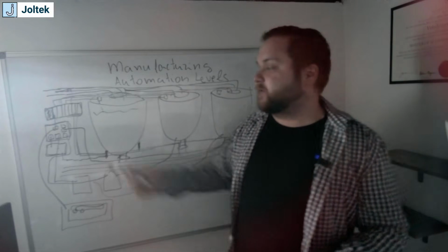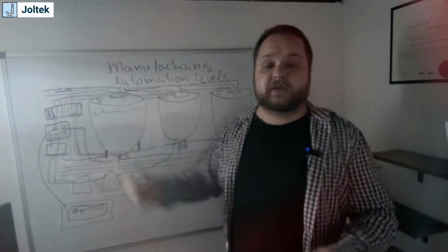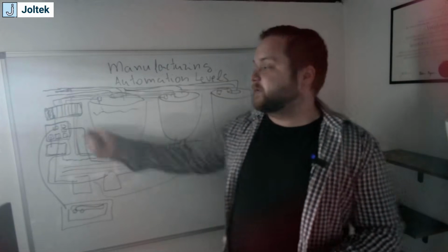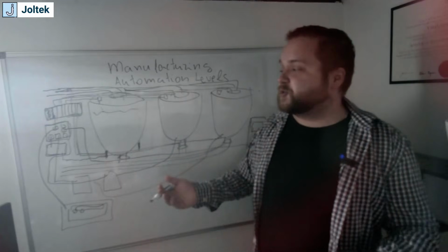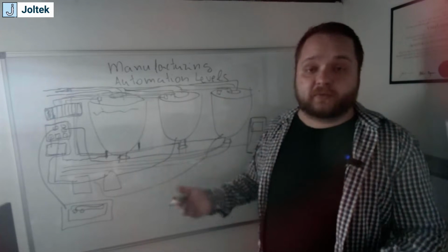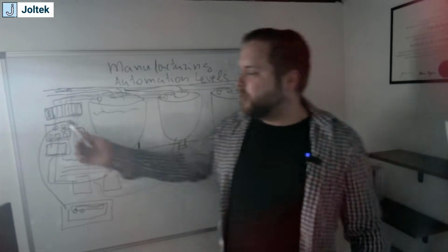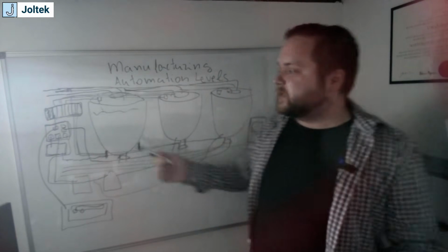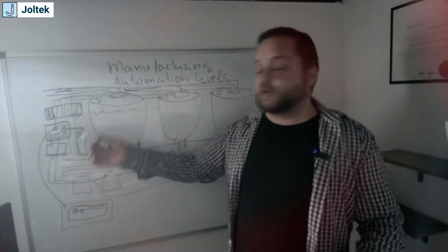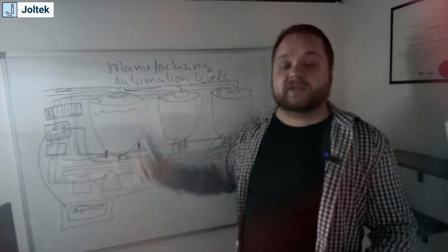Besides the fact that if you have, for example, an operator or somebody opening the electrical cabinet who decides to plug in their laptop unknowingly and introduces some kind of vulnerability, you're basically paying a lot of money to make this switch managed. And the reality is the traffic, or all of the network, should be contained within this system.